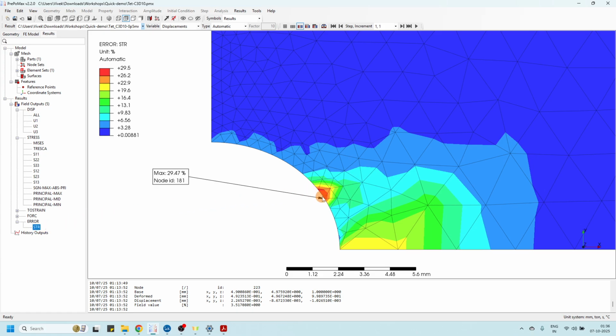That is the reason we will always see high stress gradients in this location. Irrespective of mesh refinement, if you further refine it to 0.25 mm, 0.1 mm, or 0.05 mm, this stress gradient error is not going to reduce, because this is the nature of the problem. This is the actual behavior. There is a transition from tensile to compressive, and we know this for this simple example by looking at the deformation pattern.